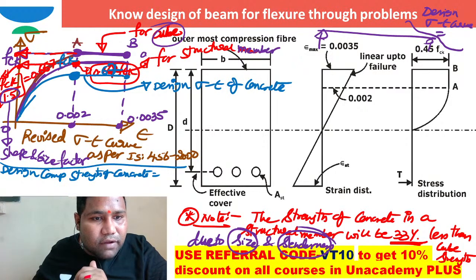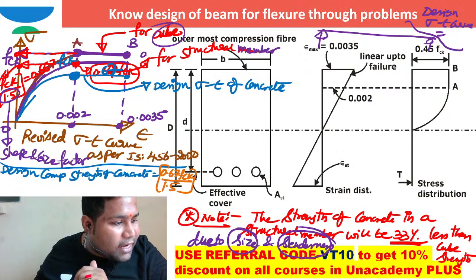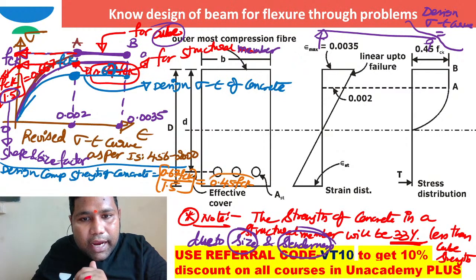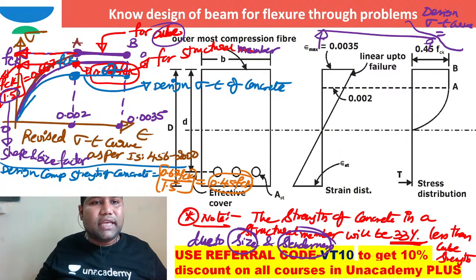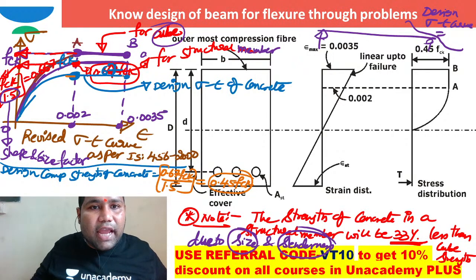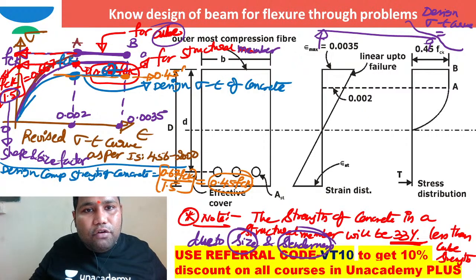We can write this clearly as 0.67 FCK divided by the factor of safety for concrete in limit state of flexure, which is 1.5. So what will be the final answer? The final answer must be 0.45 FCK, right? So I can take this strength here, it is 0.45 FCK.